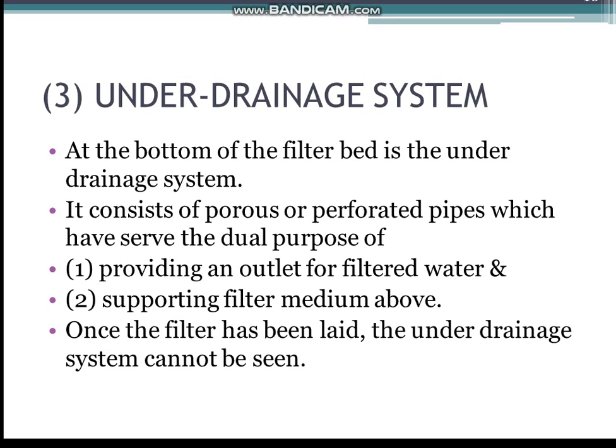Under drainage system. At the bottom of the filter bed is the under drainage system. It consists of porous or perforated pipes which serve the dual purpose of providing an outlet for filtered water and supporting the filter medium above. Once the filter bed has been laid, the under drainage system cannot be seen.